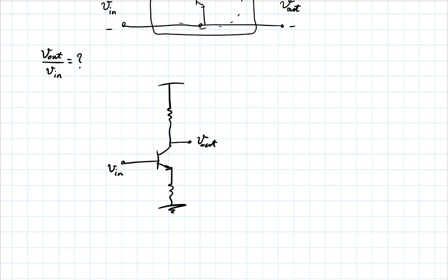Depending on the mode the transistor is in, for instance, this is going to change, right? If I have not specified Vin, maybe I've applied a Vin that's so large that it has driven this into saturation, right? Like one of the examples. That's possible, because if I increase Vin, I increase the emitter current, that increases the collector current until this Vout comes down enough that it gets too close to the emitter voltage, and then the transistor enters saturation. So you're saying, well, things would maybe change if I go from active to saturation.